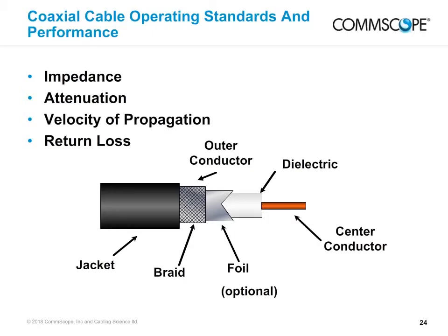Impedance is the resistance to alternating current flow measured in ohms. The nominal impedance of the transmitter, receiver, and cable must match precisely for a system to work at maximum efficiency. An incorrect match will produce a poor return loss situation. Video coaxial cables have an impedance of 75 ohms. Impedance values of 50 ohms and 93 ohms are available for other applications such as antenna or data cables.